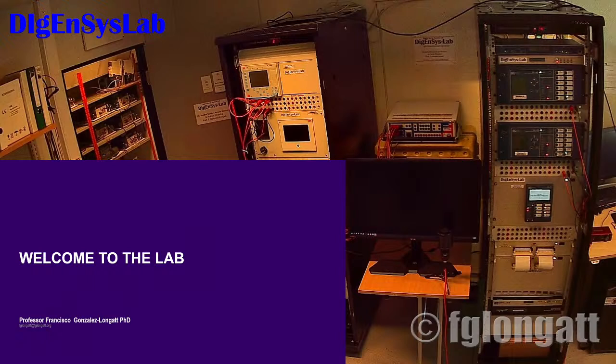Just give me a second. I will remove this, or should I keep it? If the value is crazy, remove it. Yeah. Okay. Because it is bigger than the operation time, but we can say that it is the clearing time, from when the fault starts until the relay operates. Okay.